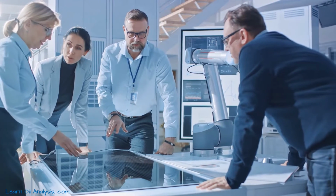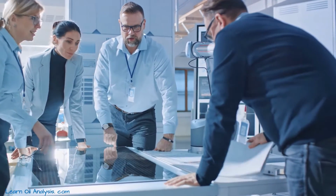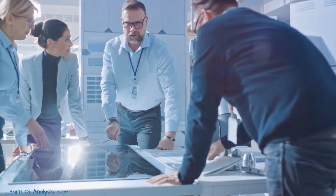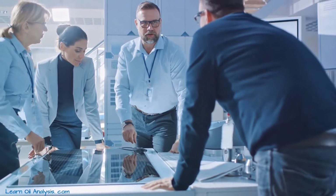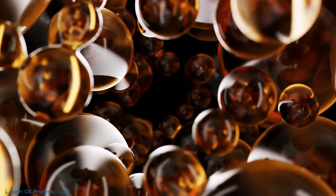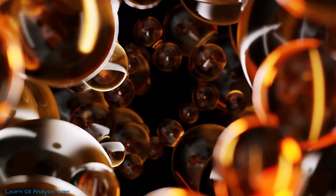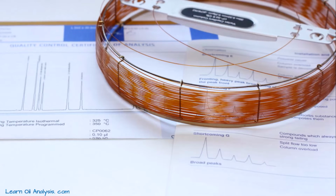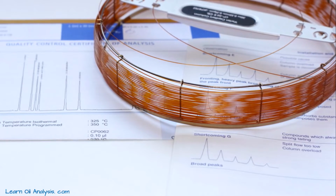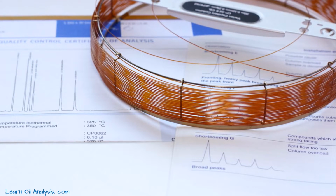The first method we'll discuss is the key gas method. This technique focuses on the relative proportions of key gases, indicating the main ones at play. By examining the levels of hydrogen, acetylene, ethylene, methane, ethane, and carbon monoxide, we can gain insights into the type and severity of a fault. We have already covered much of these examples, such as acetylene linked with arcing and ethylene with high-temperature thermal faults.